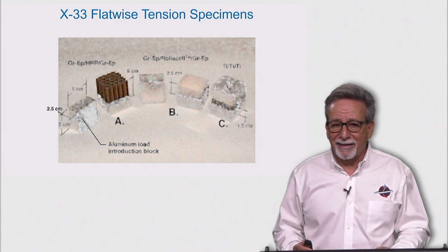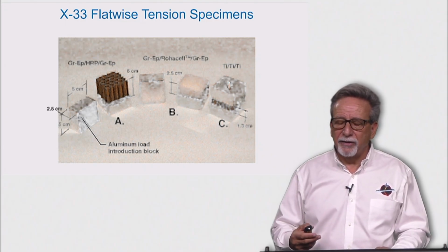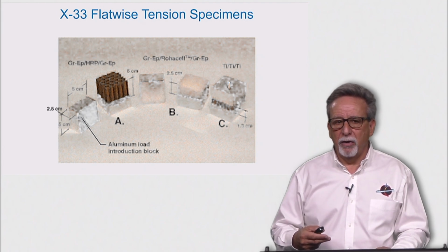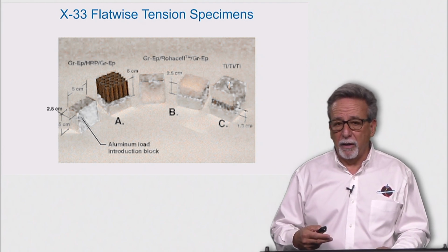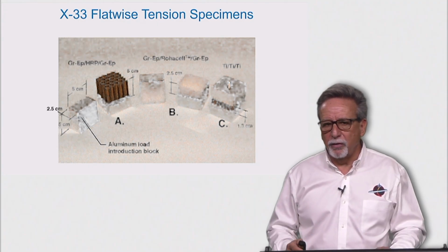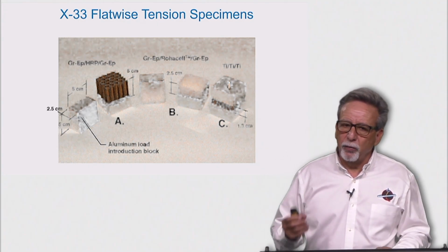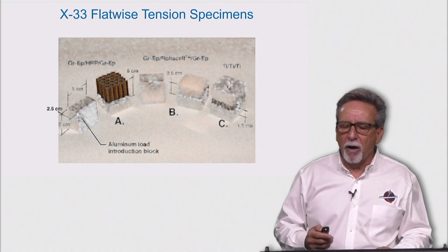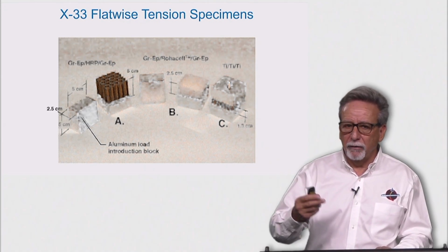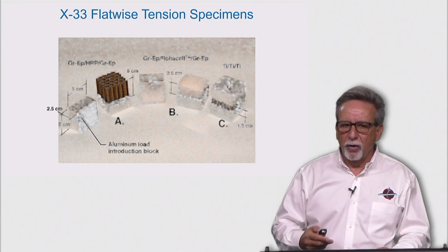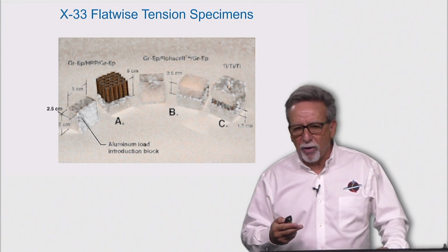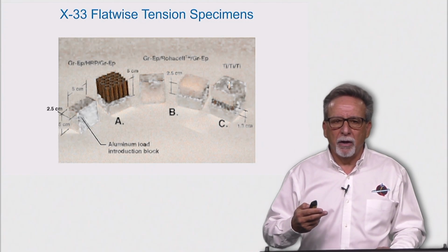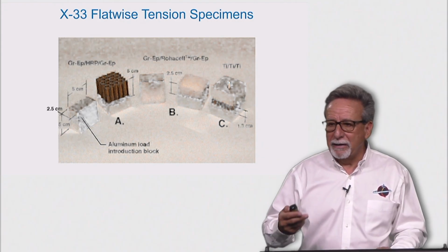If this were to occur, the condensing liquid would cause a slight drop in pressure within the cells of the honeycomb and suck additional air into the honeycomb cavity, allowing it to condense. This process was called cryopumping. The liquid would be trapped within the honeycomb core, and then it would expand rapidly, exponentially, upon heating, for example, when the level of liquid hydrogen drops in the tank. This increase in pressure would cause the honeycomb core to explode or delaminate.